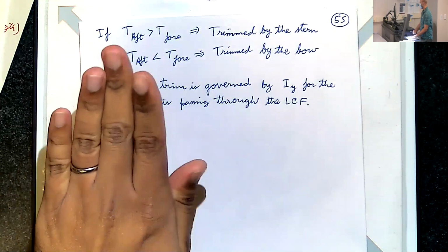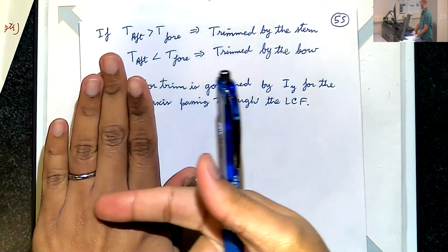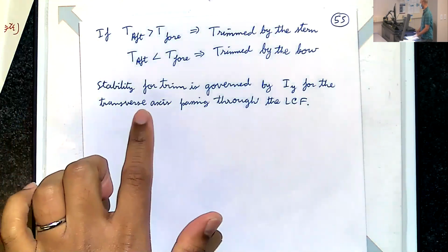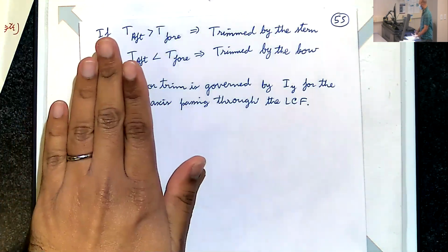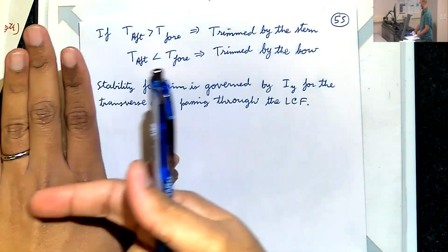When we talk about pitch, we talk about Iy, the transverse axis. And since we are pitching about the LCF, we have to have this axis pass through the LCF.